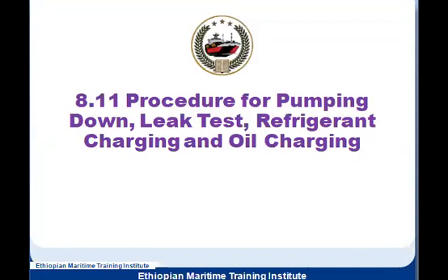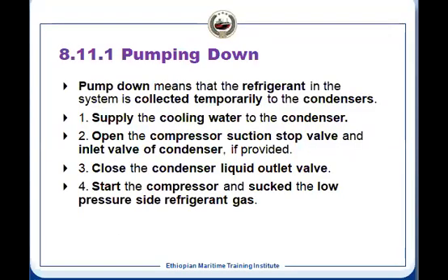Now there are certain things we need to know: the procedure for pumping down, leak test, refrigerant charging and oil charging, because we have the refrigeration for cooling and dehumidification. Pump down, what does it mean? Pump down is a temporary collection of the refrigerant in the condenser.